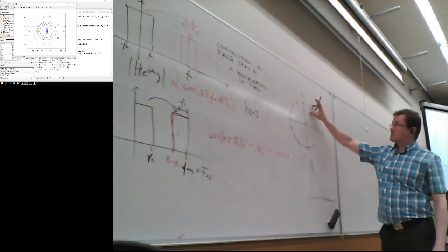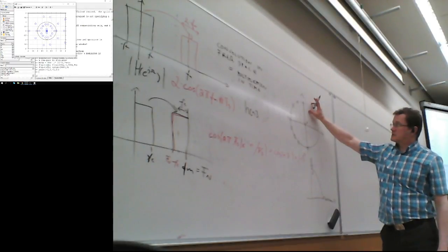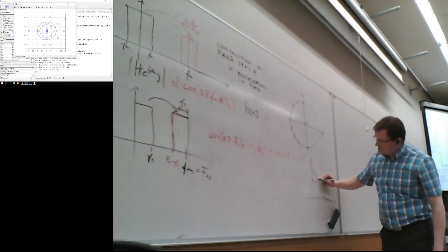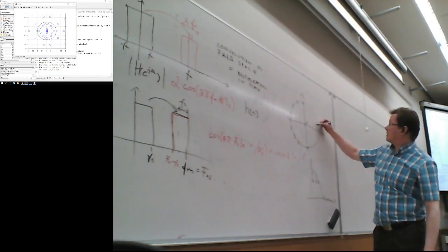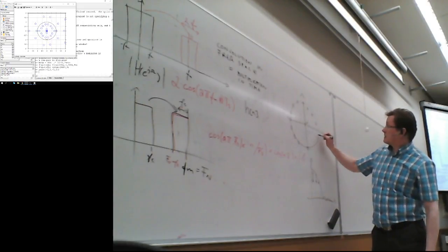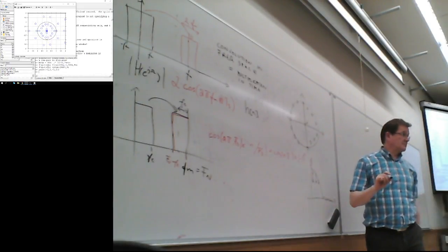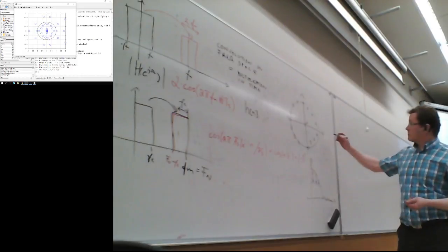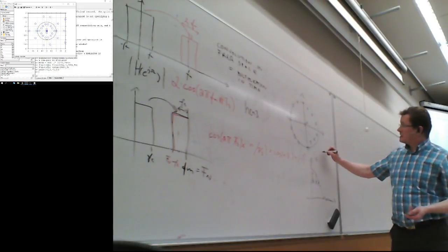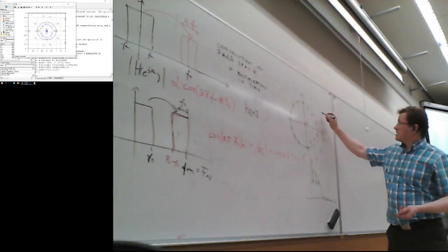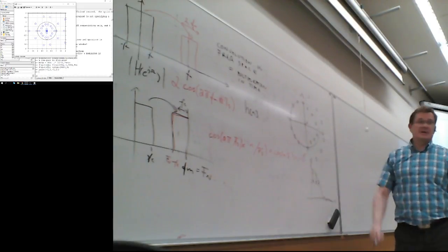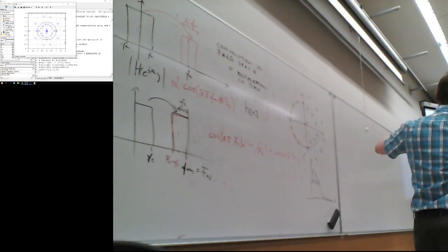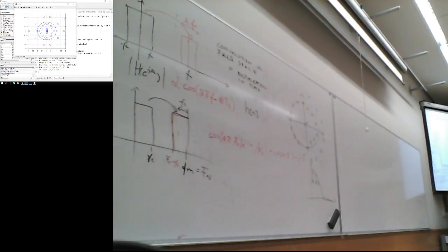The only way is to put some zeros here, but not on the unit circle, but close to that point, so we can actually pull some frequencies down, like putting those here. Okay, but then basically it will go like that. But on the other hand, for the symmetry, you also need the reciprocal pairs of those poles here, not the zeros. So that's why we have them on both sides, but there are also some computing accuracy issues on this one.